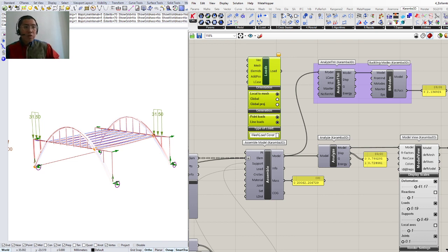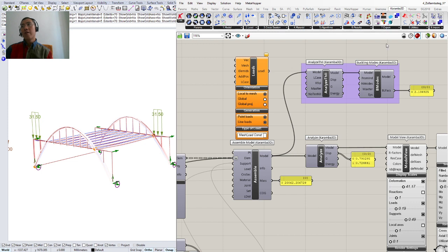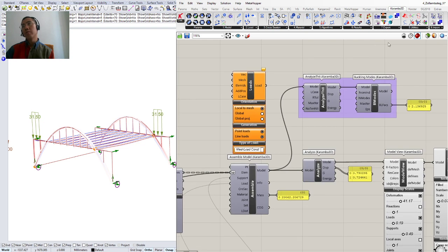And then there was one additional question about options of exporting and importing. Yes, this is something that we will be going through. As you can see on my screen, we have in Karamba the default exporter, which exports the model to Robot and RFEM or RSTAB. This is a DSTV file, which is a STEP file format, which can then be imported from various software. There are third-party plugins such as Geometry Gym, which I have here, for example, where you can export into different programs such as Robot, SAP, Sofistik, SpaceGass, Strand, for example. We will be looking at these at a future stage and maybe also looking to collaborate with some of these developers.